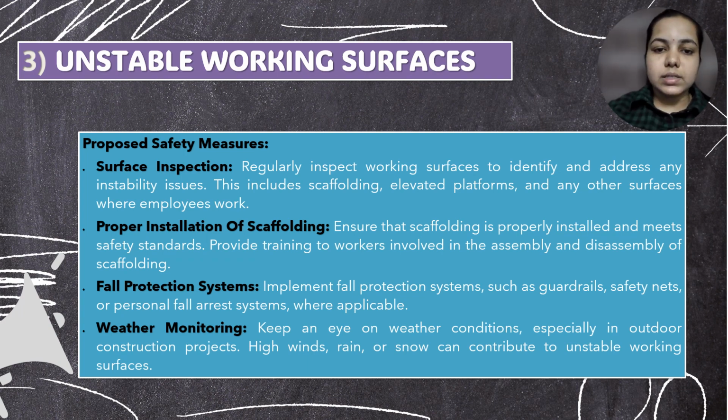The last point is weather monitoring. Keep an eye on weather conditions, especially in outdoor construction projects. High winds, rains, or snow can contribute to unstable working surfaces.